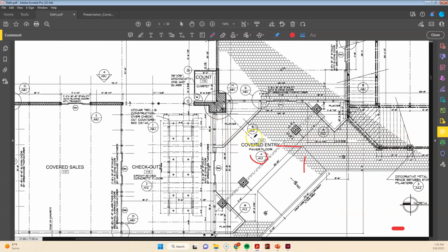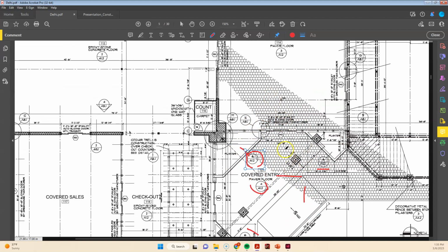So here on sheet A12, detail 6, we're going to cut through a planter. It also pertains there, and it pertains there. So there are 3 planters, and those are the details. Right in this area, I don't see any other call-outs. We start to walk through the door. There's the door call-out. So when we find the door schedule, we could find out more detail on that door.